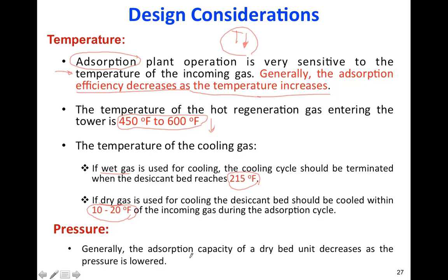As for pressure, as I said, adsorption works better at higher pressure. If we decrease the pressure, we will decrease the efficiency of adsorption. This is another point: it is better to keep the pressure up and the temperature low.